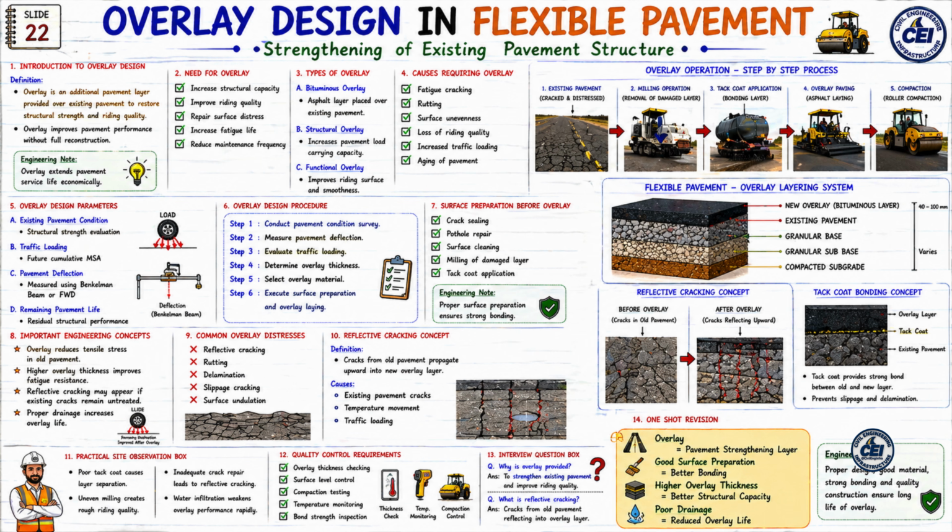Now let us look at the 8th topic. 8. Important engineering concepts. Overlay reduces tensile stress in old pavement. Higher overlay thickness improves fatigue resistance. Reflective cracking may appear if existing cracks remain untreated. Proper drainage increases overlay life. And these concepts are most important in practical pavement rehabilitation.